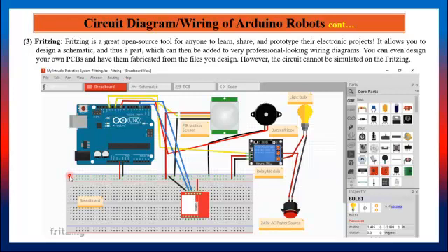Now other components tap their power from these two. From the SIM800 you can see connections to pin 3 and then pin 2. Also from the PIR motion sensor you can see the connections to the Arduino digital pins. You also see the relay module where we tap the ground voltage and the 5 volts, and the signal also runs to pin 13 on the Arduino.